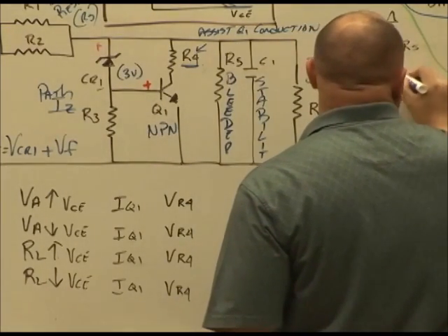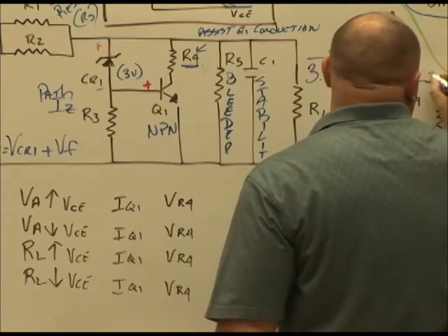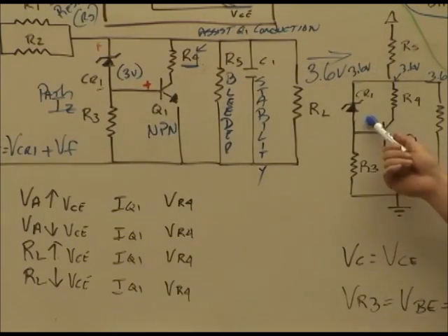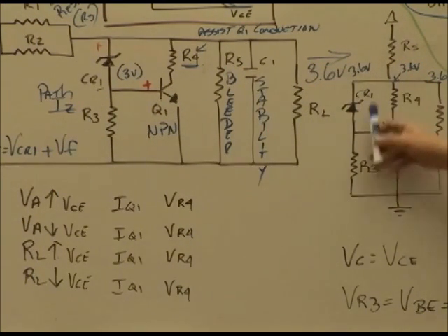They should, because that's how it works. 3.6 volts here, 3.6, and 3.6 at the load. Because what's common in parallel? Voltage. Nobody said series this time. Good job. So what sets the output voltage? Doesn't it? Yes, sir. So the zener branch current is relatively constant, isn't it? Yes, sir. And the big change happens here to the load.